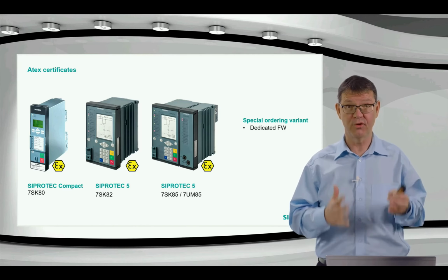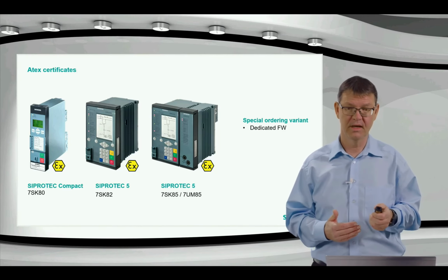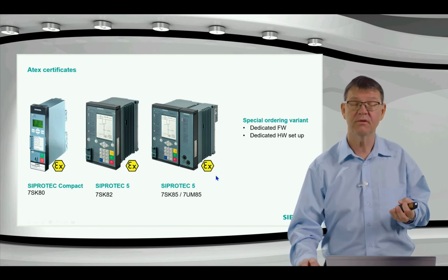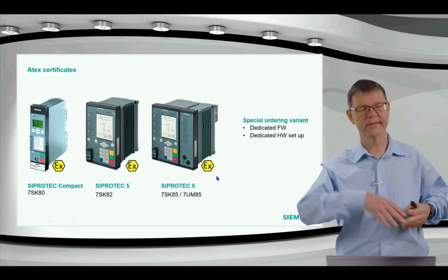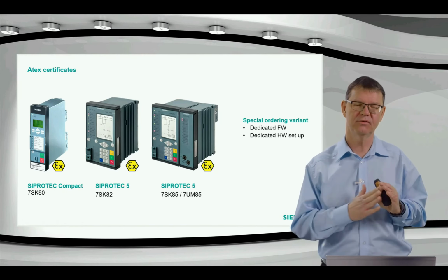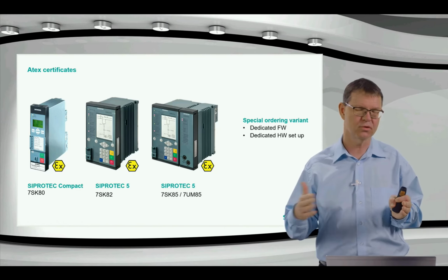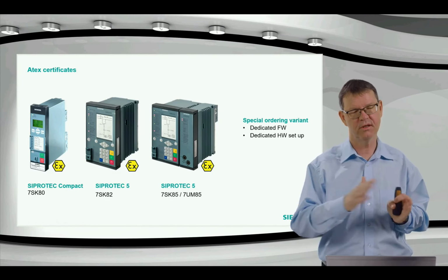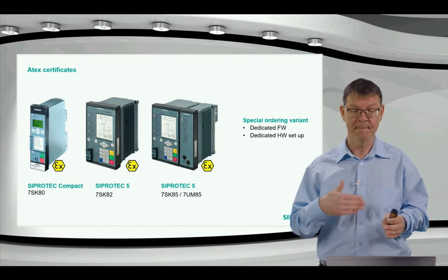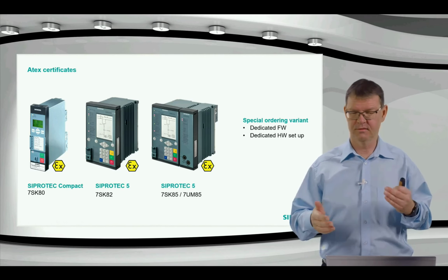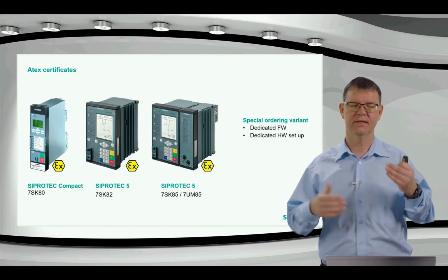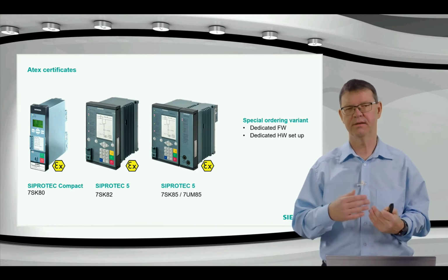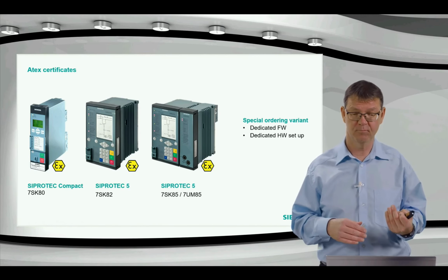And we have a dedicated firmware which has this ATEX certificate and a dedicated hardware setup. So this is especially for our modular devices. That means you cannot just select whatever you like as a hardware setup. You have to choose out of a certain range or group of devices. So we made some setups from just a smaller device to a bigger one with more IOs, for which we calculated these failure probabilities and for which we then started to prove that we fulfill all these ATEX requirements. Basically, what is behind this is SIL level 1, which we must fulfill.